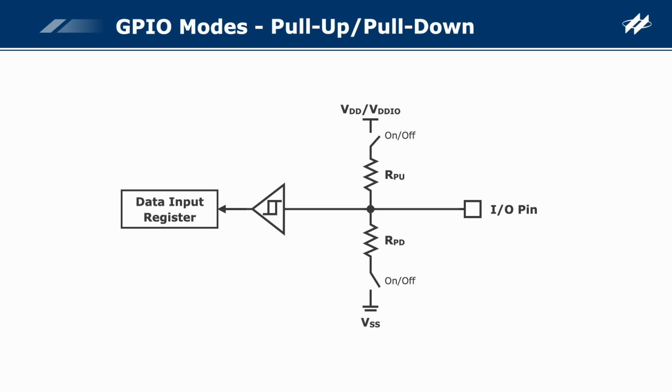The pull-up and pull-down functions are used to enable the internal pull-up resistor and pull-down resistor, as shown in the figure. The internal resistors are weak resistors. Taking the HT32F52352 as an example, the internal resistance is about 46 kiloohms.